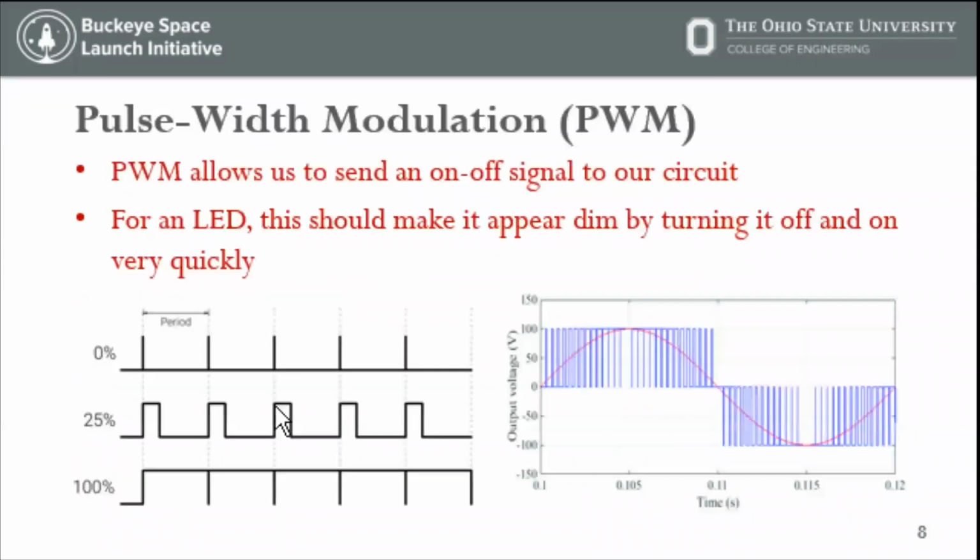Okay, I apologize. Take a step back. Let's go ahead and delete this. We're going to go to the glow Arduino circuit that we pulled up earlier. You see that the code's a little more complex. Now we're using some of that control software. So it's saying count up by 5 from 0 to 255. Then we're going to set pin 9 to that value. We're going to wait, and then we're going to keep going all the way up to 255, then reverse, go all the way down to 0. Oh, I'm still on the PowerPoint. I'm sorry.